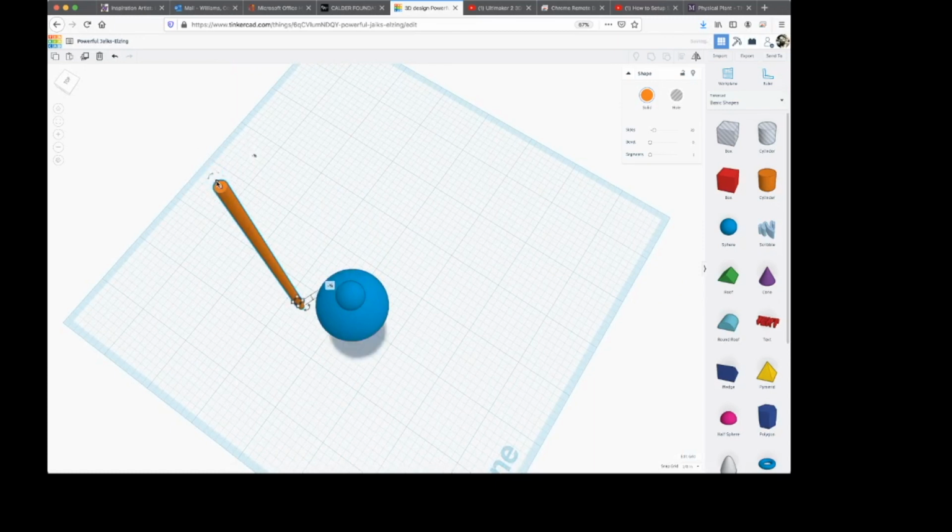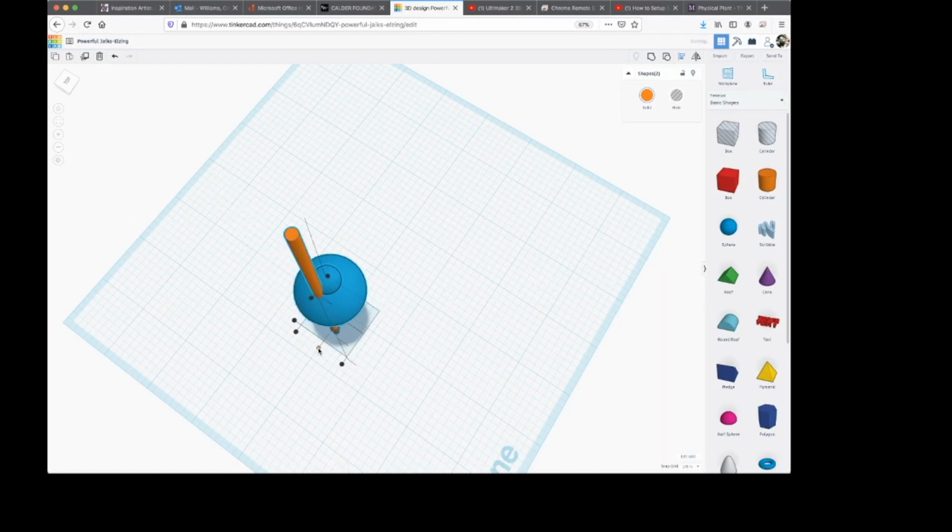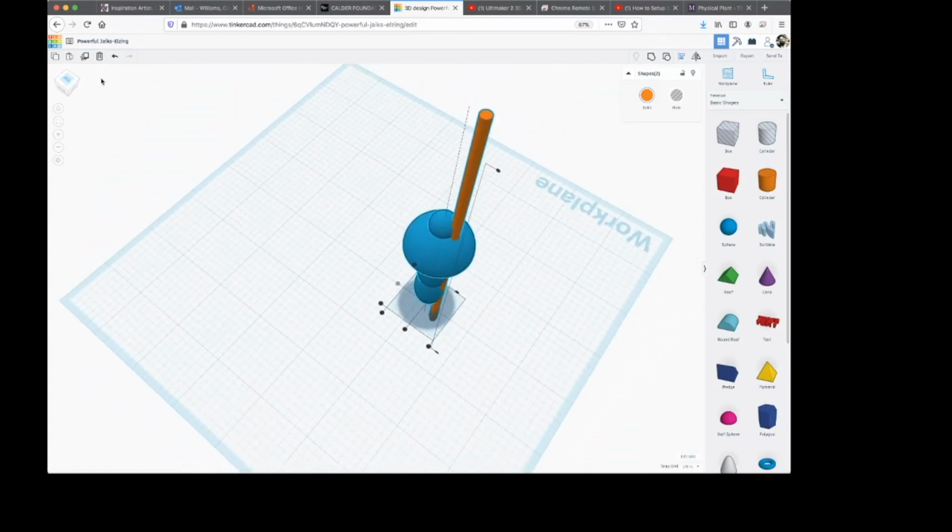So to do that, again, we're going to use our alignment tools, hold shift, and then click the blue form, turn on our alignment tools by coming up to the top right hand corner and clicking the 4th button, or use the shortcut L. In this case, I want to click on this center paddle or handle to align it to the x-axis, and then let's rotate that around so I can see the other handle that I need, and then the other center handle to align it to the y-axis. So now that pole is going straight through the form of the blue shape that I've made.